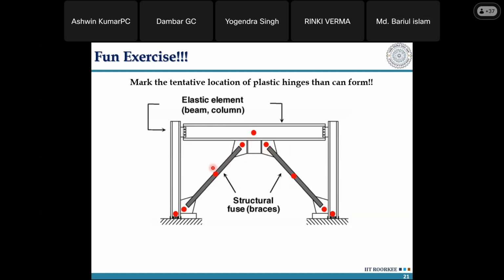So from pre-buckle to post-buckle, pre-buckling is where this brace yields in tension and this brace undergoes buckling, to a point where this brace is still yielded under tension but this one has reached a post-buckle domain where the compression capacity is reduced too much. Then there is an increase in the vertical as well as horizontal forces in the members. That will cause hinges to easily form at this location if you don't design the beams for these.